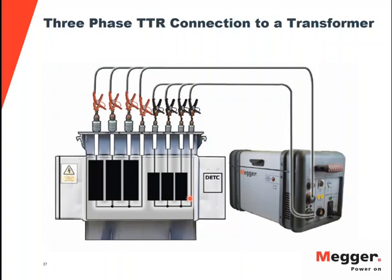But with winding resistance, sometimes the resistance can be really small for the low voltage winding, and meeting that criteria of 2% within the phases or 5% from the nameplate is hard, because you are trying to measure a few hundred microohms, or a very small value, and 2% of that could be just overtaken by the instrument accuracy. So in those kinds of cases, you may want to have a higher tolerance, or you may want to have a tolerance not in percentage but in absolute value.